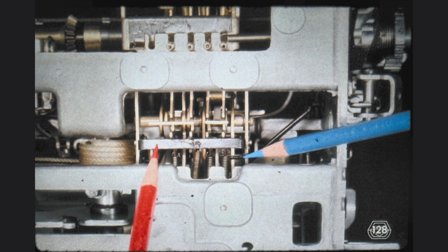On very old machines, you might add flat clips to the shaft or beam of the restoring bail when you need to shift the bail motion further to the front of the machine. Be sure to check this 1/4 millimeter clearance on all the operational interposers of your machine. Test the restoring interposer action, making sure that in the process you try both lugs of the restoring bail.